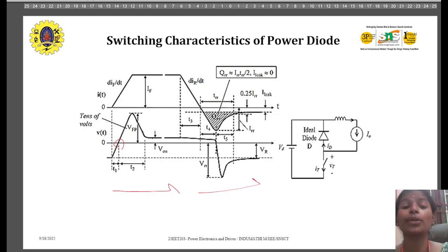When the diode goes from forward conduction to reverse bias, stored charge carriers continue conduction for a short time, and this causes reverse current to flow even through the diode, which should block it. So here we have storage time. The storage time is when reverse current stays high while stored charge is removed, and transition time is when reverse current reduces to zero.